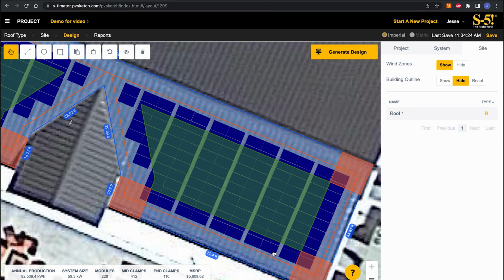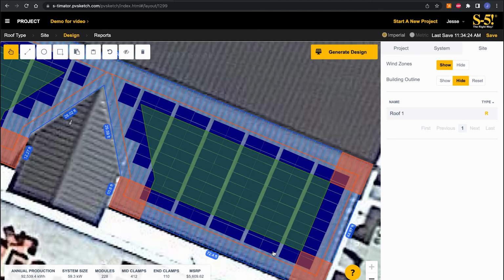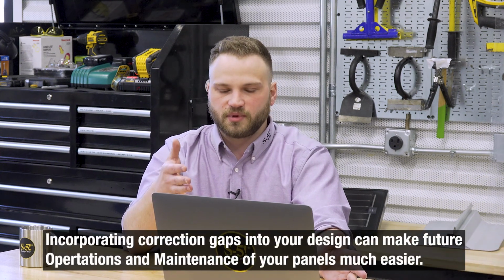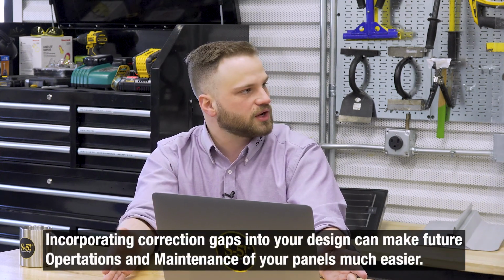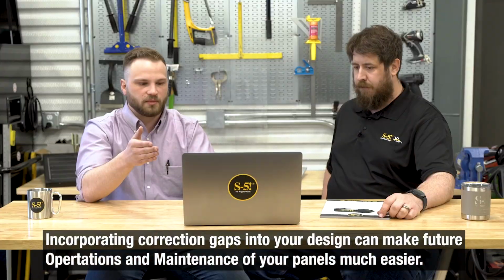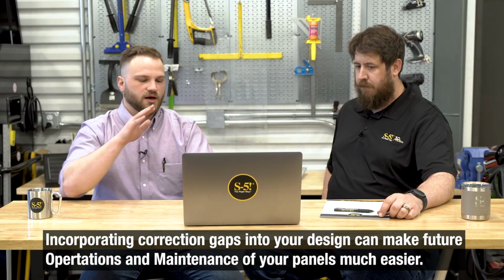This is very common to see in the field, and actually in a lot of cases is desirable. You might not get that 100% or 99% roof coverage that sometimes is desirable, but having walkways every so often allows easy access to any module. If you need to go up there and maybe provide maintenance on a module, adjust wiring, maybe a module even needs to be removed, this makes that much easier. And maybe you just want to go up and admire your beautiful solar array.